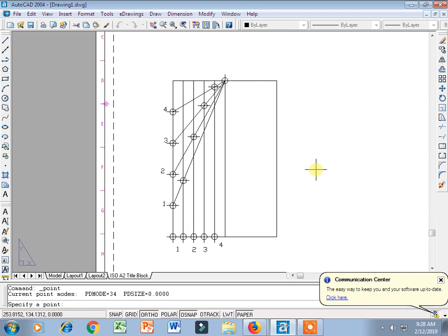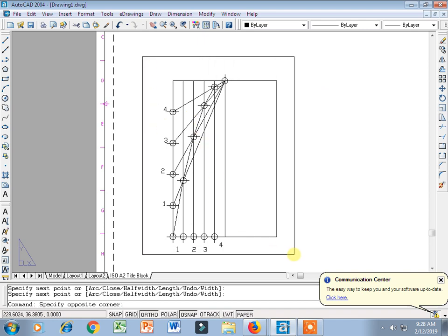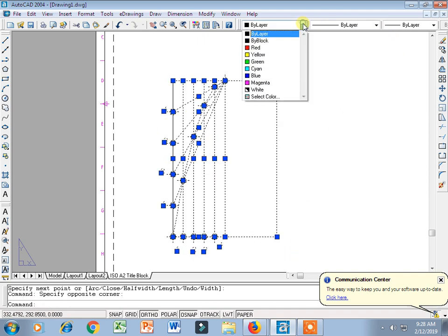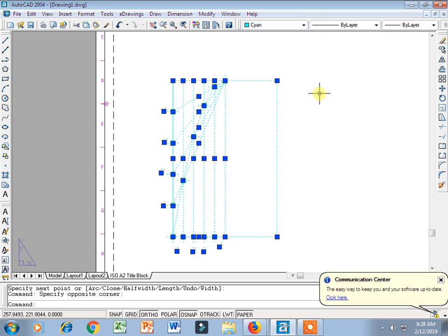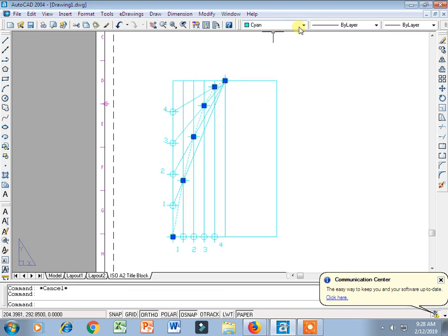So we have to start the curve. We have to start the curve from this P1, P2, P3, P4. We will go to the polyline command to join the curve. Go to polyline, select it, start, click here, then P1, P2, P3, P4 and P5, enter. Now we will select the entire sketch. We will have the construction lines in a faint color, any color of your choice. Then you select the curve and make this color somewhat different.